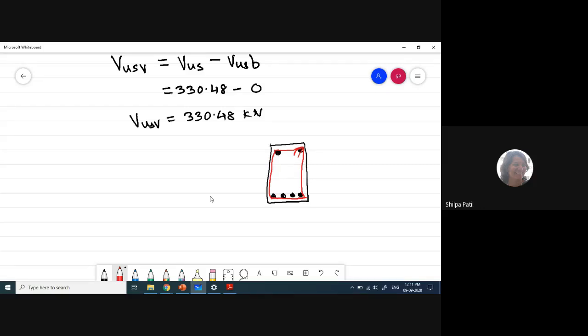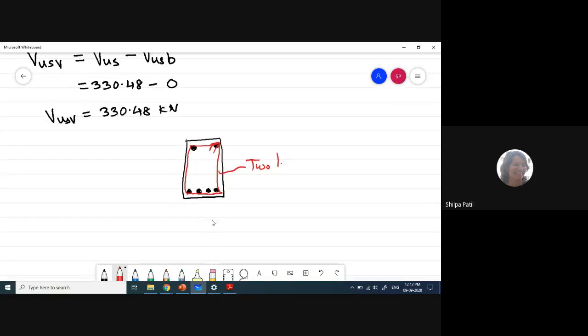So this is actually a frame of steel bar which we are forming. This entire frame is called a stirrup, vertical stirrup, which is specifically used for your shear reinforcement. And if you consider there are 2 faces and there are 2 bars, so it is called two-legged stirrups.